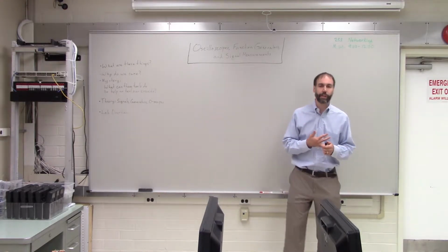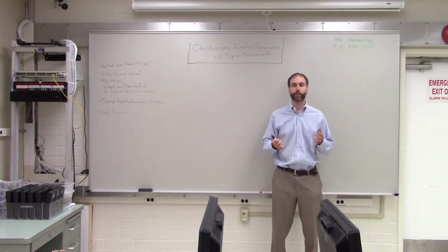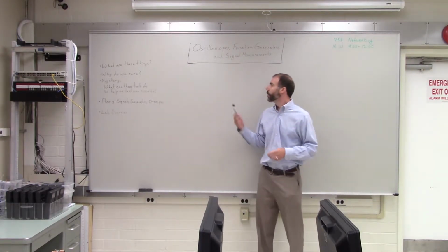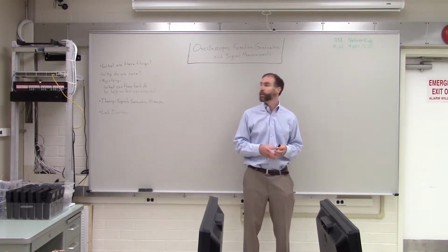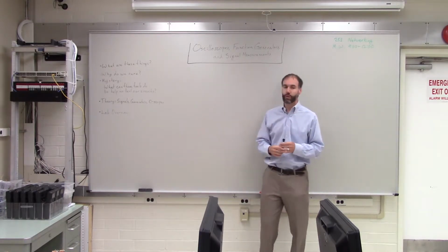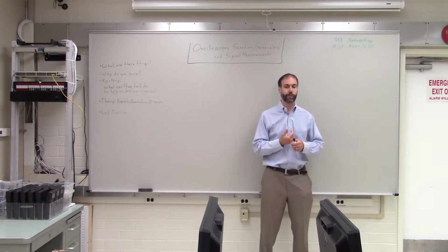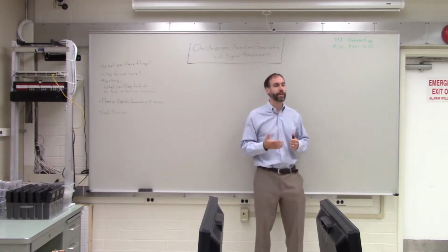And then there are many different types of electrical signals as well. There can be signals encoded as voltage, signals encoded as current. So many different things qualify as signals. Okay? We are going to be particularly interested in electrical signals. Function generators create different types of electrical signals. They create different shapes of signals, different frequencies, different amplitudes, and we'll see how to adjust all of those and create those tonight. And then oscilloscopes measure electrical signals.